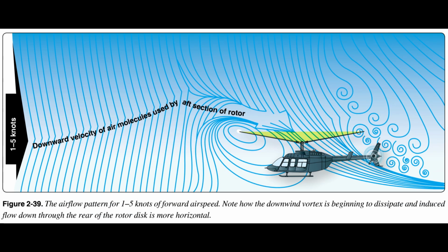Translational lift. Improved rotor efficiency resulting from directional flight is called translational lift. The efficiency of the hovering rotor disc is greatly improved with each knot of incoming wind gained by horizontal movement of the aircraft or surface wind. As the incoming wind produced by aircraft movement or surface wind enters the rotor disc, turbulence and vortices are left behind and the flow of air becomes more horizontal.